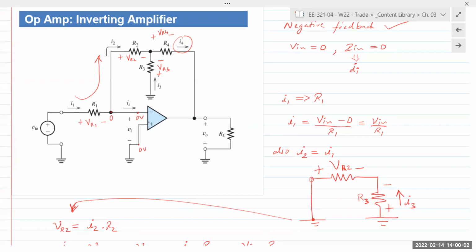So one final important point before we end class today. When you build a circuit like op-amp, what is the input impedance of an op-amp, ideal op-amp? Infinite, right? When you build a circuit using the op-amp, the input impedance changes. So the inherent properties of an op-amp do not apply if you connect external components.